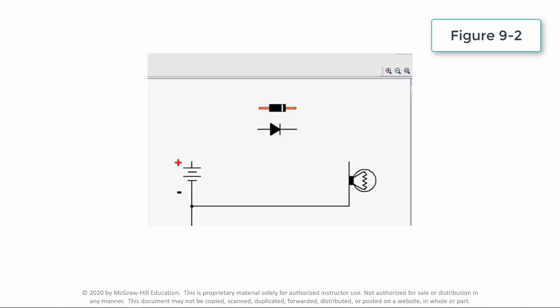The two basic operating modes of a diode are forward bias and reverse bias. A forward bias voltage forces the positive and negative current carriers to the junction and collapses the depletion region to allow current flow. A reverse bias voltage widens the depletion region so the diode does not conduct.